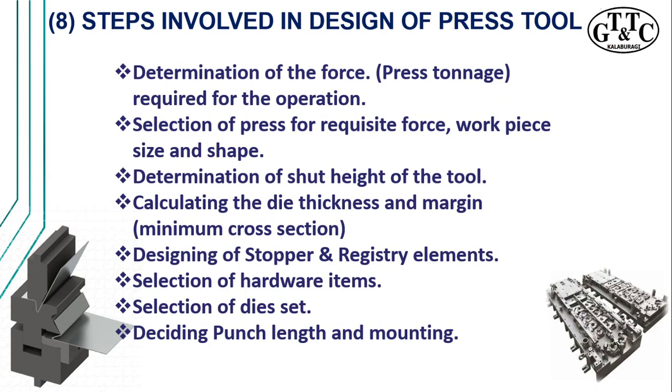And the second one is the selection of the press for the requisite force. What is the required force? It is very important that you select what type of press, because based on the component studies, as a designer you have the right to question the customer about what type of press this particular tool will be loaded on.